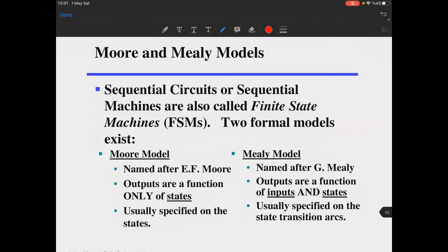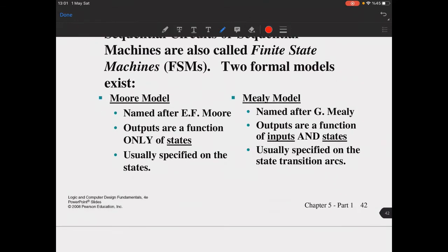Maybe the Mealy model can be much more straightforward, but you should keep in mind that Moore models are easier to code or implement, and usually hardware systems are generally based on Moore models, taking the reliability issue into consideration. But the best choice is mixed models, of course. You depend on which are the critical parts, critical outputs, critical states, and you optimize the system.